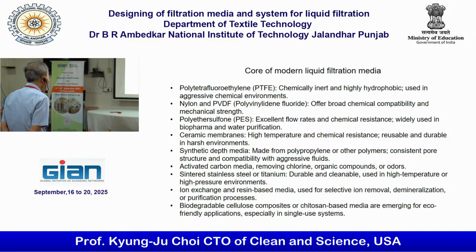Nylon, PTFE, and then polyether sulfone is a good one. So ceramic membrane and synthetic depth media made out of polypropylene and polymer, or activated carbon media. This is really good. Activated carbon media, removing chlorine, organic compounds, and odor. See, in air filtration, for removing odor, we use a lot of activated carbon. This is a common material.